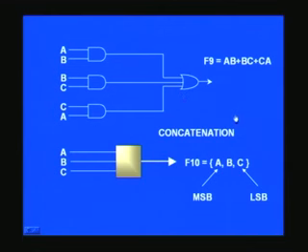And next example we can consider is how to concatenate different signals. For example, A, B, C are each 1 bit signal. You can put it, concatenation is just putting it together in the order that you want, and the flower brackets is the one which signals the compiler that this is concatenation as such, and you separate the signals, and one may be tempted to say variables. That is because of our past habits linked to the C language, and here I do not speak in terms of variables, but as signals as such.